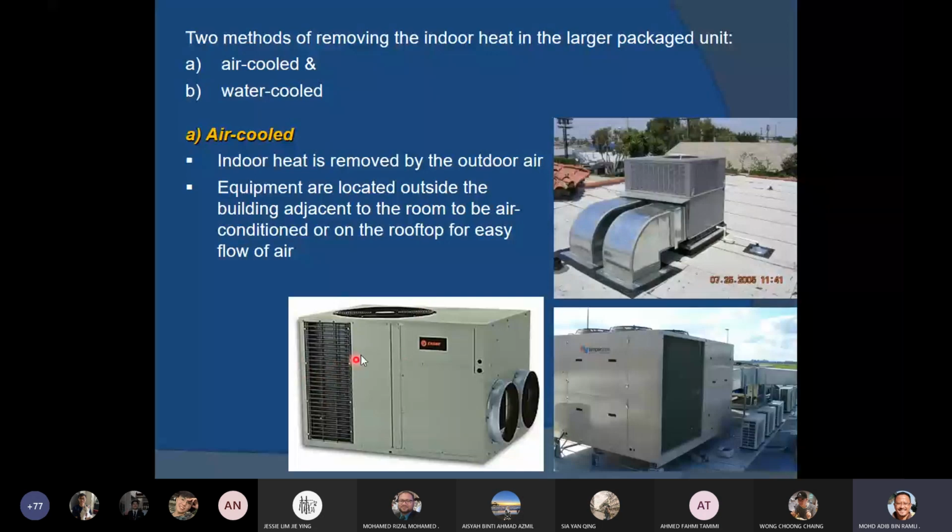And then it will carry the heat from the condenser coil and goes up and release it to the atmosphere. So basically, in this system, air is used to cool the condenser. Okay, just the outdoor air. So basically, the fan sucks in the outdoor air, and then the outdoor air carries the heat from the condenser and then releases it back to the atmosphere. All right.